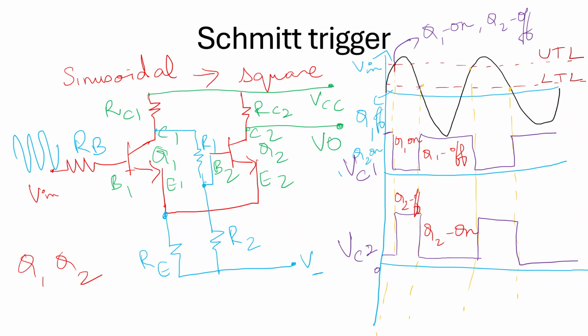When the transistor Q1 starts conducting, the voltage drop at the collector of Q1 drops to minimum. This negative going signal is coupled to the base of the transistor Q2 through the resistor R1. It reduces its forward bias and thus the emitter current and hence the voltage drop across the resistor RE.